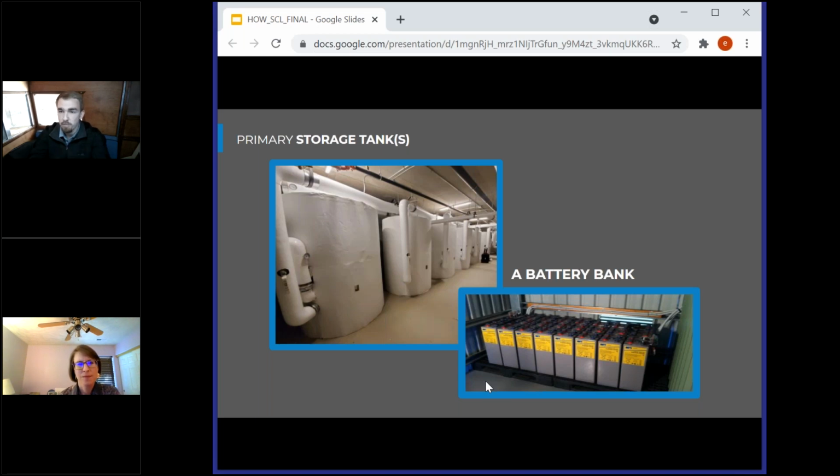So your heat pump's going to be much larger, and at the same time, your heat pump's going to have to ramp up and down really quickly, which, with the physics of what it's doing to the refrigerant behind the scenes, is not going to work efficiently, and it's not going to end up being a reliable heat pump. So you want to be able to basically operate your heat pump at a really low rate throughout the day while your storage handles these peak loads. And there will be more losses, but they'll be more than offset by your heat pump working more efficiently than an electric resistance or a gas heater.